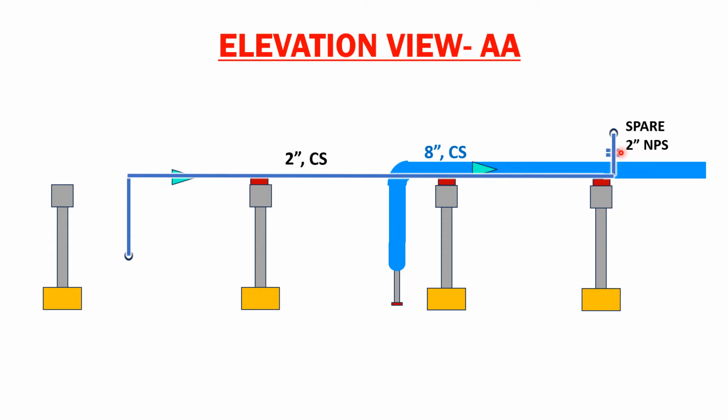So this is the exact point where my new piping and old piping are connected, right? See, this line is the old piping, and this line is the new piping, correct? This new line connects to the existing piping with the flange, and this flange is over here. So this is the tie-in point for me. In this scope, we only have one joint where the line is connected to the existing line, at only one location. That's why the tie-in point is 01.